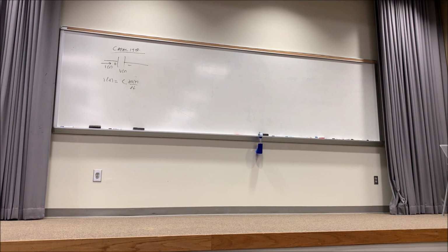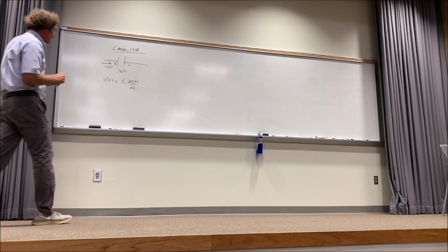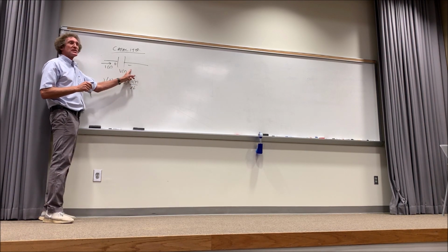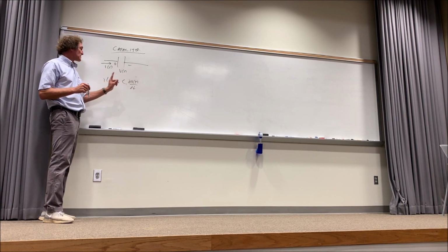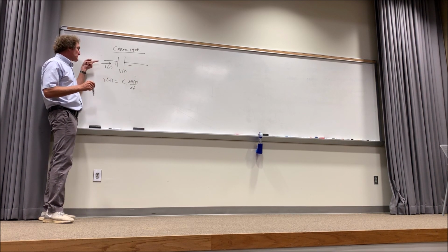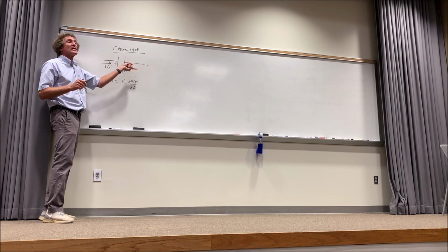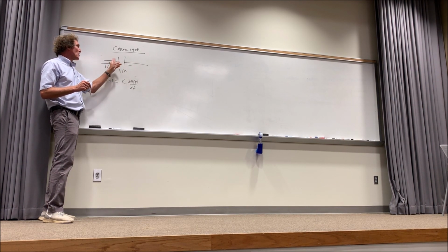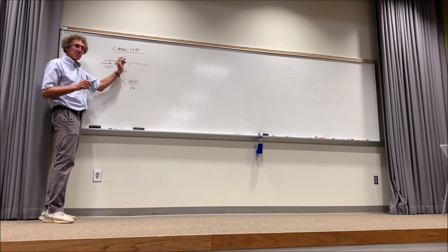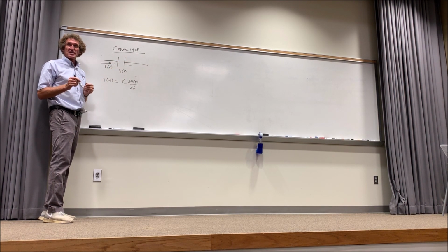Now, one thing you'll notice, if the voltage across the capacitor doesn't vary, a DC voltage, there is no current. And current is flowing in that direction. So literally, think of it as flowing right through there, even though real charge doesn't move. It's called a displacement current, where charge on this plate will displace charge on this plate and cause a current. Do you follow me in this class?